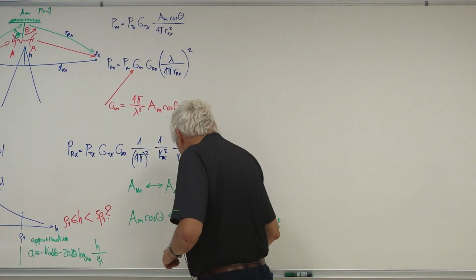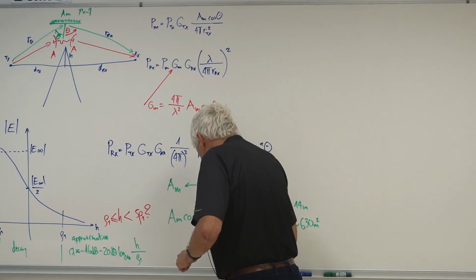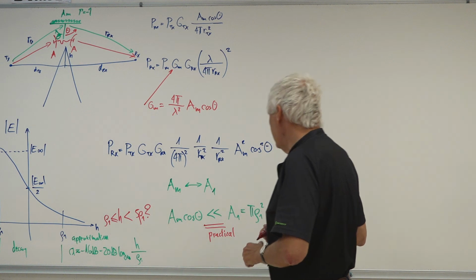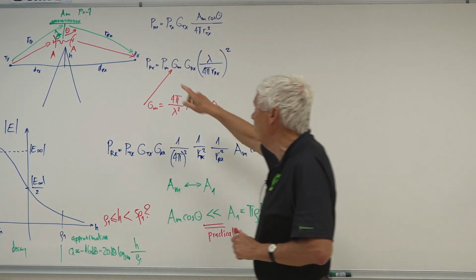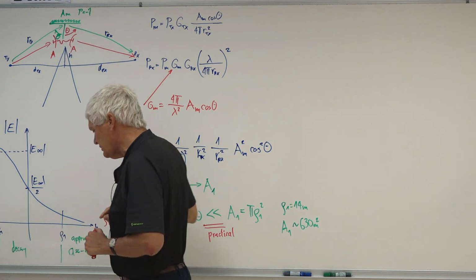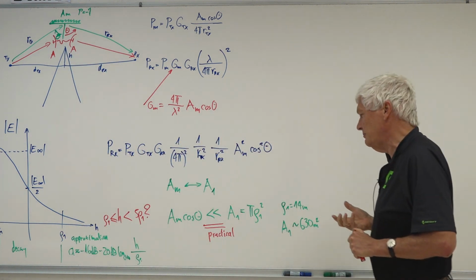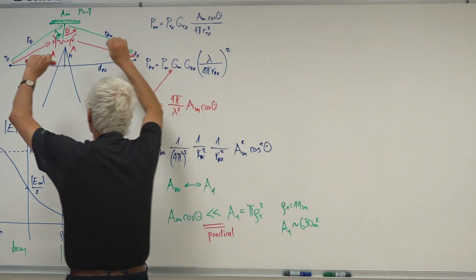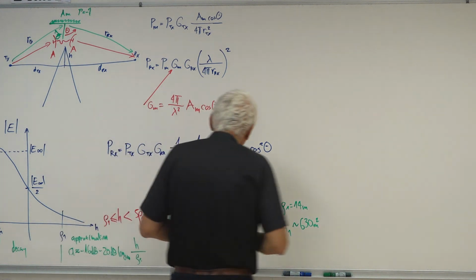The practical solution is that this is much smaller. If this holds true, then for the summation of all phasors over the surface, all Huygens sources on the mirror, we have an in-phase condition, of course when the mirror is perfectly adjusted for the direction of the receiver.